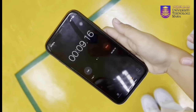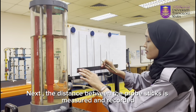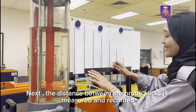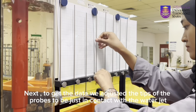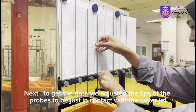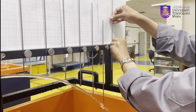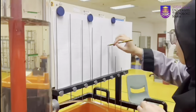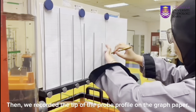We set up the timer until it reached the height that we wanted. Next, the distance between the probe sticks is measured and recorded. Next, to get the data, we adjusted the tips of the probe to be just in contact with the water jet. Then we recorded the tip of the probe profile on the graph paper.